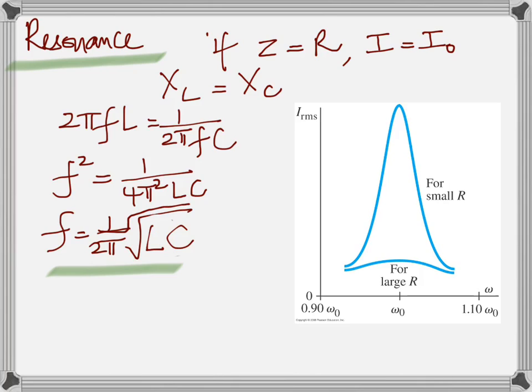So when you're tuning your radio, what you're doing is you're actually changing the capacitance. You have inductor, resistance, and capacitance. Inductor and resistor are fixed values, but the capacitance, I'm talking about manual tuning now. Remember the manual tuning where you turn that knob? It's actually a gang condenser. It's several plates of a capacitor and then several other plates that you can either move into or out. So when you tune that thing, you're either moving the plates out or in. You do know that the capacitance depends on the area of the plates. The overlapping area. Are you with me? So if you move it in, you're increasing the capacitance. If you move it out, you're reducing the capacitance.